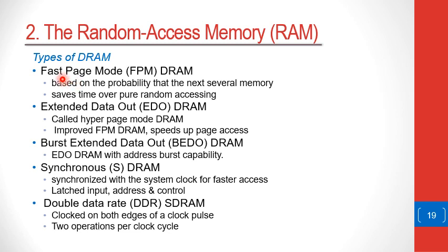So what happens is the DRAM simply reads, as always, in fast page mode, in the sense that when a row is selected, it reads all the adjacent columns' data out. This saves time as opposed to purely random access if the processor requires all of this adjacent data. However, it will tend to waste time if the processor does not need to access all of the adjacent data.